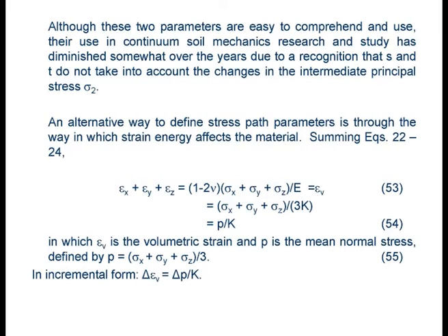In fact, you can easily show that if you take the normal stresses acting in three orthogonal directions at mutual right angles, and you take the average of those three normal stresses, no matter which direction you choose, how you rotate it, it is always the same. That is the one quality that it has that is nice. So when we talk about mean normal stress, we never talk about direction. There's no need to talk about direction. Is that all right?